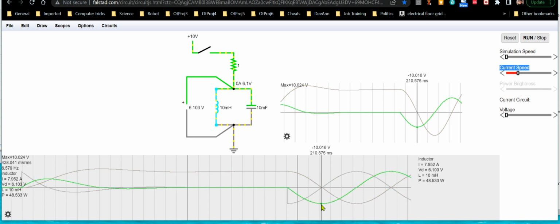So remember I said in this stage, the inductor is generating an infinitesimally larger voltage across it than the capacitor has in it. Well, here, just the opposite. It's generating an infinitesimally smaller voltage across it than the capacitor has, because the capacitor is now the source of voltage. The inductor is trying to resist that because it's trying to maintain its current at 0, and it's resisting the current increasing. But again, it can't do that forever.